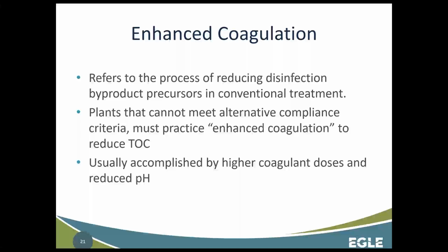And then I think one of the things that is a little bit less technical but still very important is just economics. In some cases it's going to be more cost effective, even though a polymer might be more expensive per unit. You're going to end up with cost savings because of something like sludge production, or maybe there are some really large treatment plants nearby that are using ferric, and you're able to do bulk purchasing with them to get a better price. There could be a lot of factors that go into that, I suppose.